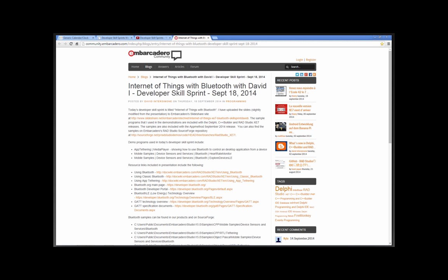And so the first long number in the GUID, it's reserved by Bluetooth 1800 hex to 18FF hex. After that, then there's custom device. Like my oximeter for my health labs shows up as 1900.